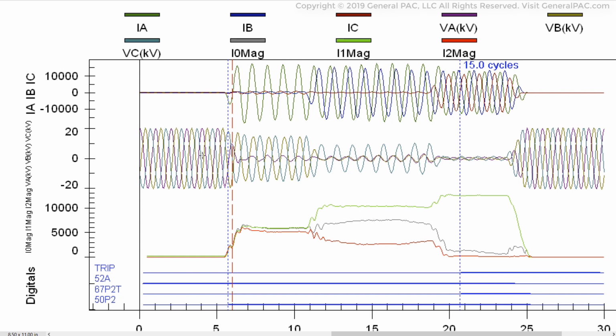And even on the voltages, we can see that the remaining phases, meaning phase B and C, are relatively intact. They're definitely depressed, but the phase rotation is relatively intact, meaning it's purple, then green, then teal. So purple is depressed, then green, then teal, right? So relatively intact. But then at this particular point here, something happens, right?